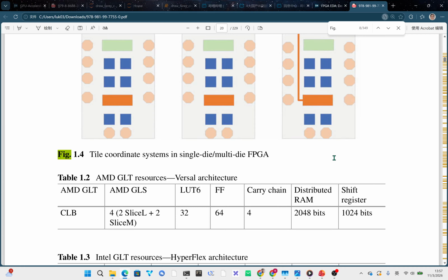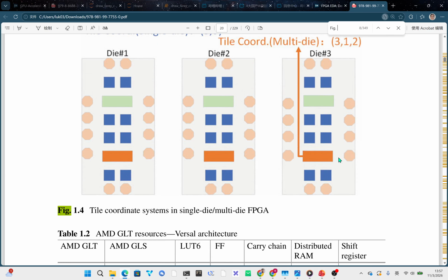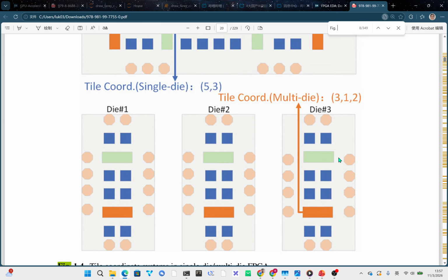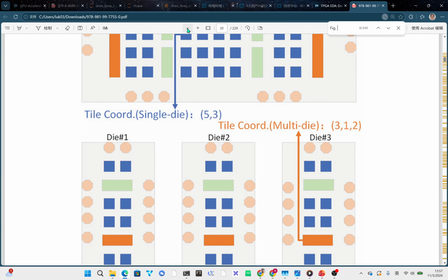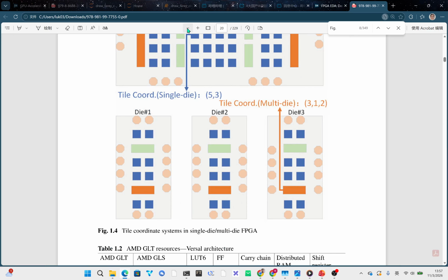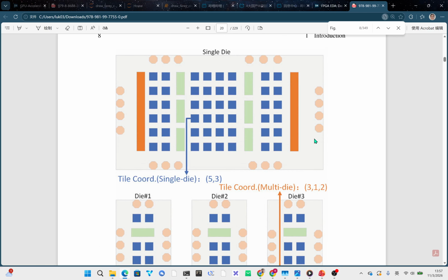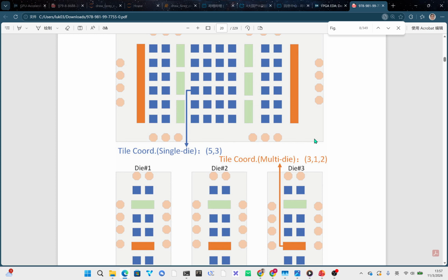But the logic blocks themselves haven't stayed stagnant either. We've completely moved past just basic logic gates. Yeah. Today, we have modern heterogeneous tiles. Integrating hard cores right into the fabric. Instead of forcing engineers to build an entire processor out of tiny logic blocks, vendors started just embedding an actual hard ARM CPU directly into the chip. I think Altera Excalibur first did that around 2000. Which completely shifted the paradigm.